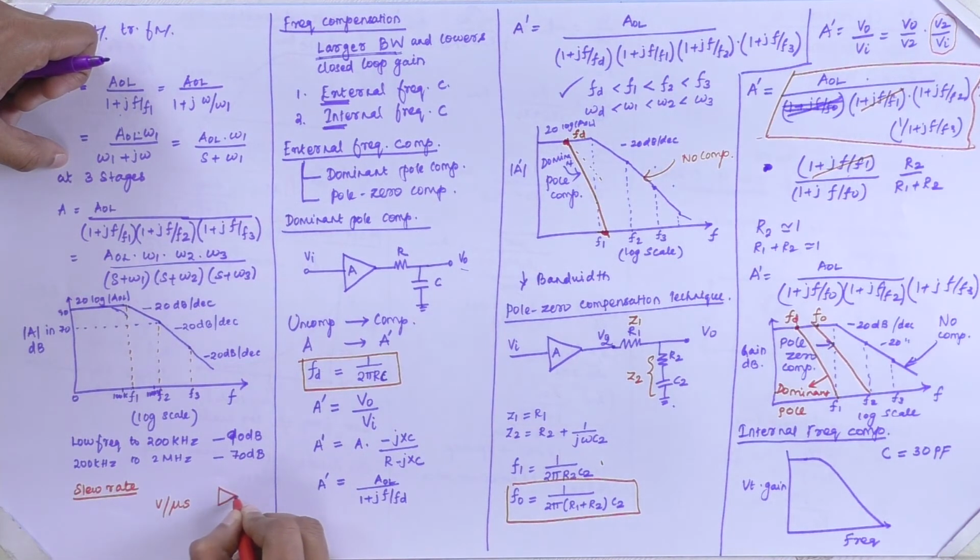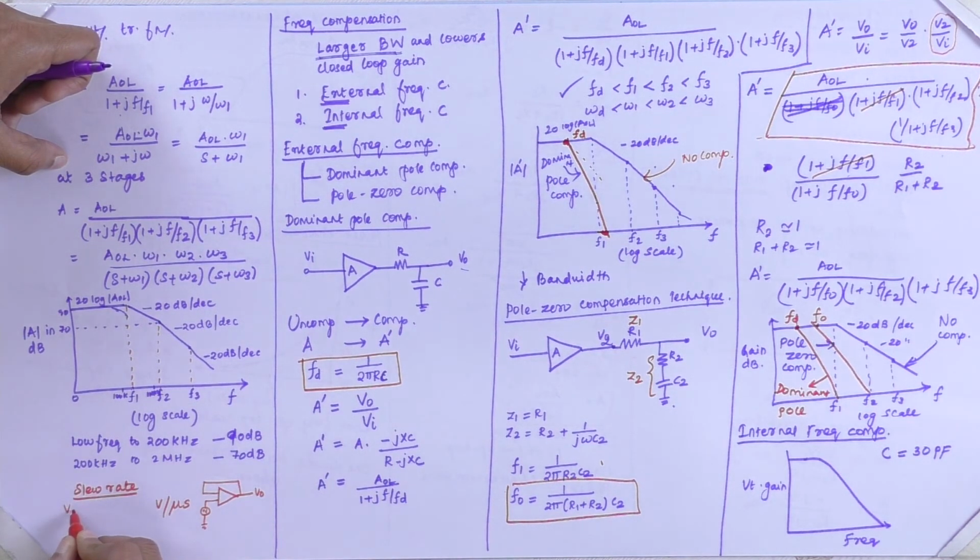Initially, for example, consider this as your operational amplifier. A voltage circuit is given, the output. So this is a normal voltage follower circuit. In that we will be giving the input signal as Vm sin omega t, and your output for the voltage follower, as I already mentioned, V0 is equal to Vi. So here V0 is equal to Vm sin omega t.